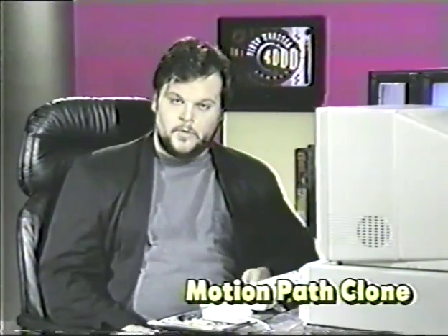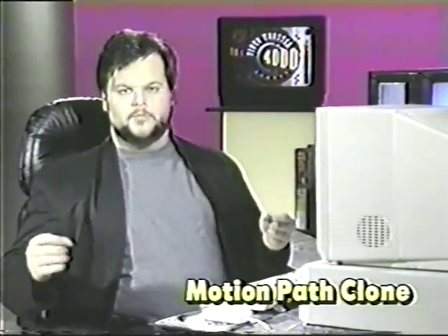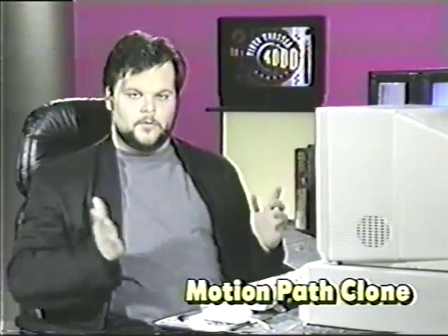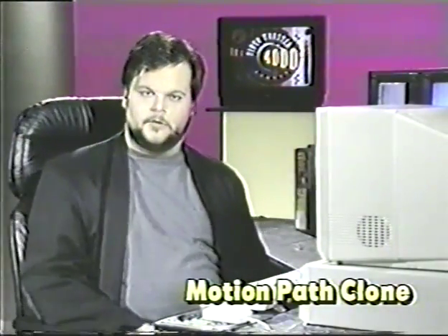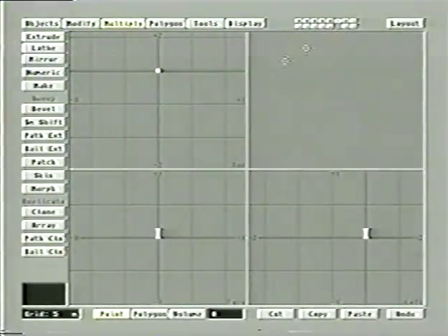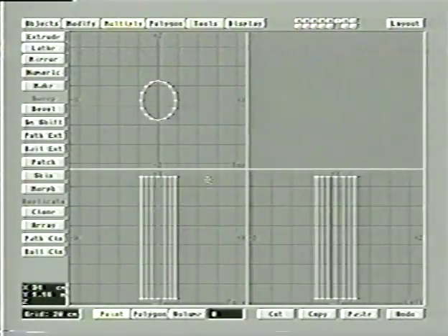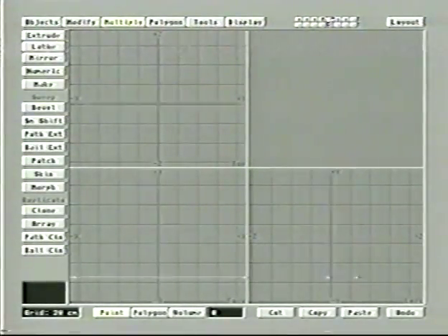Now let's use the motion path option here. What we're going to do is I'm going to want the pylons to move so that there's one on either side of the road, and they move along the side of the tunnel here. So what I need to do is I need to set up the pylons properly. Let's do that by picking just as the active layer the pylon itself, and then finding our tunnel.